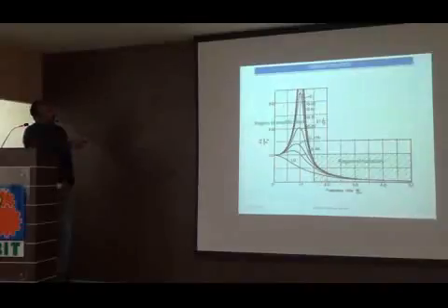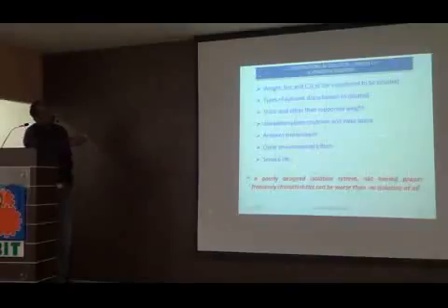But whatever may be the isolator, you should know that the region of isolation is beyond root 2 times. That is the thing. So, by introducing an isolator, what happens? There is a zone where you are amplifying the input. So that also you should take care of, and you should know very well that in this zone your system is not failing, but you are gaining advantages in this zone. Let us see some cases.